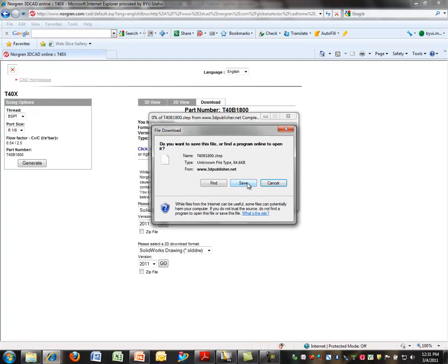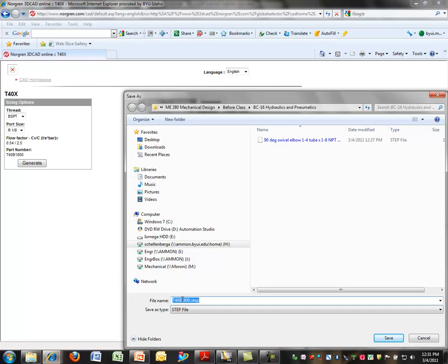And we'll download, save as, and in this case I'm going to give it a different part number, because the one I really want to purchase is a pneumatic silencer, 1/8-inch NPT, Norgren part number MS001A. That's the one I will buy that will actually fit. And the one I'm downloading, even though it's a different part number, British standard thread, at least it will look similar. We'll save that.